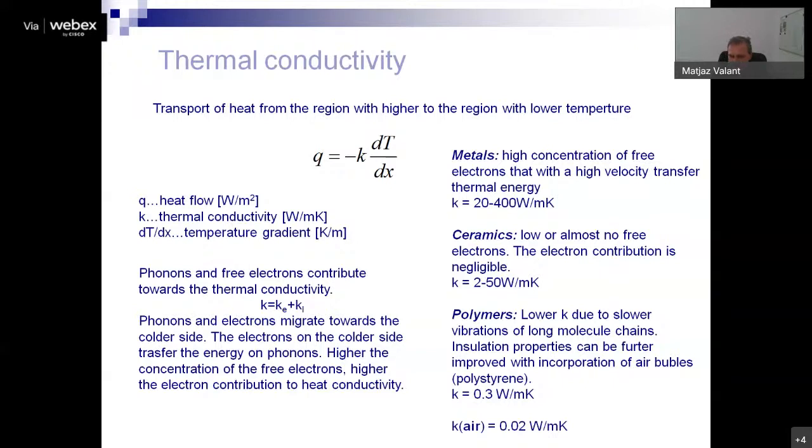However, for high temperature insulation, it is more appropriate to produce ceramic foams, where within the ceramics there would be a lot of air trapped, and that would result in high temperature thermal insulation materials. We use these materials to insulate furnaces or blast furnaces in the steel industry and so on, while polymer insulation materials are used mainly for our room temperature insulation.